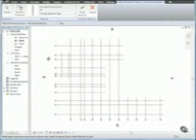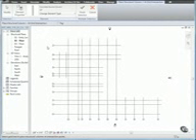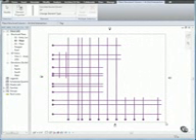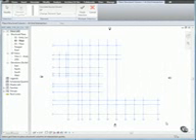Draw a selection box around the grids by first clicking the upper left corner of the drawing above the grid and then dragging the cursor to the lower right corner as shown. Then, from the Multiple Selection panel, click Finish Selection. When you do, concrete columns are placed at each grid intersection. Click Modify and let's verify the column base level.